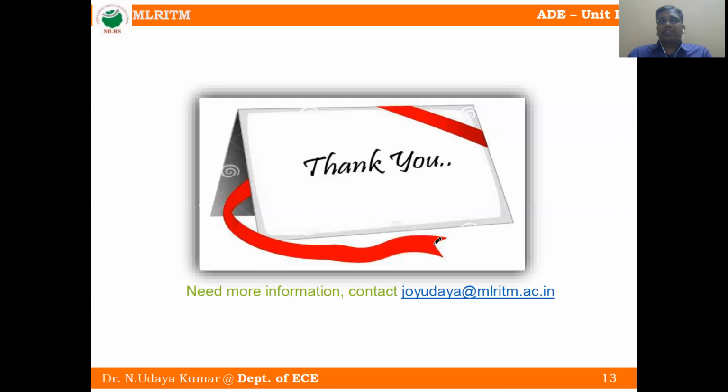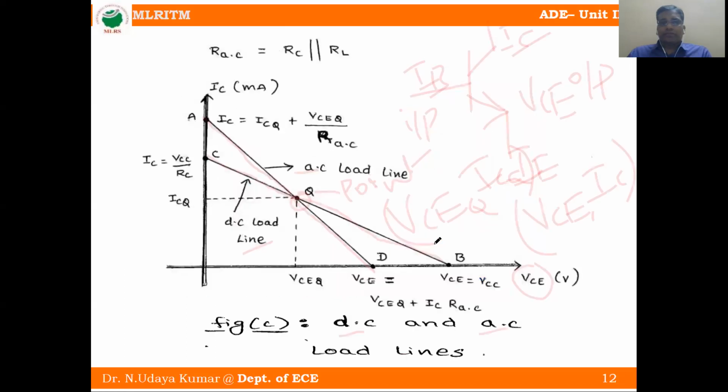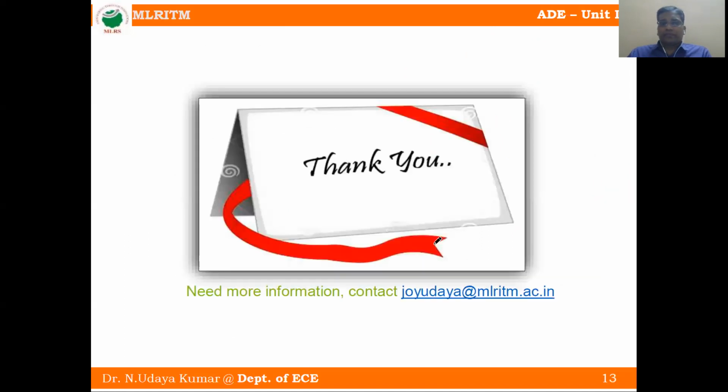Whenever an AC signal is given to the circuit, then we calculate the VCE comma IC, and we call it the AC load line. The intersection of the AC and DC load lines we call the Q point. The Q point is always taken at the middle of the active region, so that we can amplify the signal in a better way. Okay, thank you.